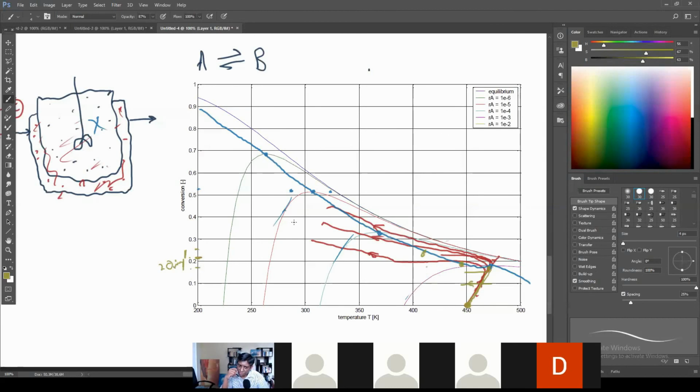And you'll do that obviously because you want to achieve your desired conversion, let's say we wanted right there, 70%. Impossible to do it without cooling, you see, right? If you just left the system alone, it can only reach there eventually. If you apply cooling, then you can get here, but it depends very much on which trajectory you choose. So if you cool too fast, you're going to kill the reaction, and it's going to take forever for you to get up to this 0.7.